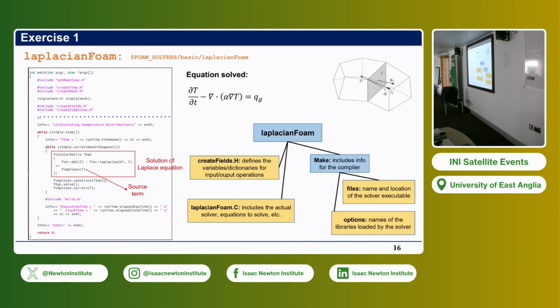Then there are a set of tools. You need to create a big block, bigger than that shape, let's say. And then OpenFOAM will subtract that block. Let's say you want to study an external flow. OpenFOAM will subtract that block from the mesh you have created and adapt all the cells close to the surface so that they are clipped in the right way. So this is a special tool for adapting? Yeah. It's inside OpenFOAM. We can talk about it, and everything is in these slides. I'm not going to cover it, but there is a specific exercise about that. You're welcome.